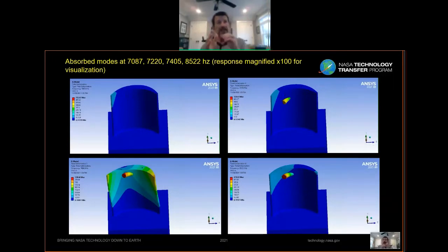We are rearranging the structural dynamics. We're moving the energy from the airfoil, which is our critical part, into our tuned mass absorber, which is completely contained within a cavity inside the airfoil.